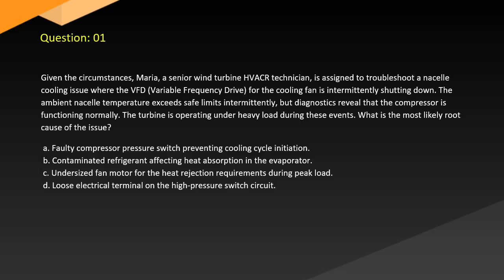A. Faulty compressor pressure switch preventing cooling cycle initiation. B. Contaminated refrigerant affecting heat absorption in the evaporator. C. Undersized fan motor for the heat rejection requirements during peak load. D. Loose electrical terminal on the high-pressure switch circuit.